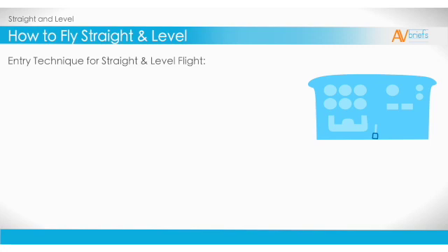Too much lift, and we climb. Too little lift, and we descend. So the saying is that power and attitude equals performance. First we set the power. Then we set and hold our attitude. You must know what attitude to set first. It's not a guessing game. For example, in the Cessna 172 you would set an attitude which is 4 fingers in height off the sun visor. So that means, there is 4 finger widths between the glare shield and the horizon.